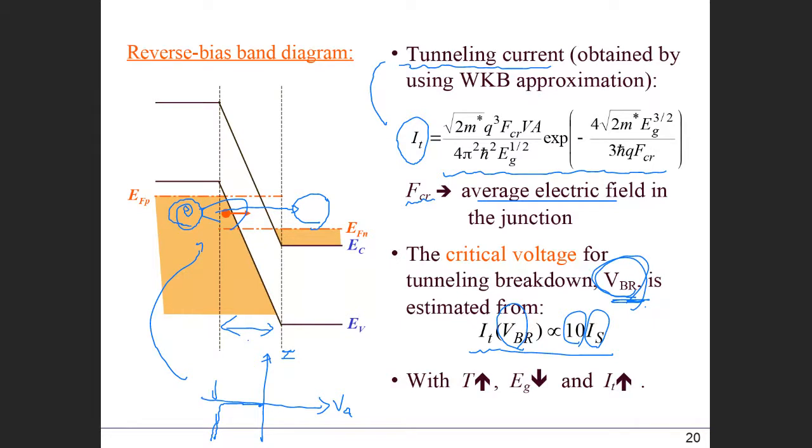For this device, we can set it so that when the reverse bias reaches a certain level, it starts to flow lots of current. Later on, I'm going to show you as an example that this kind of device is very useful to form a voltage regulator, which regulates at a certain voltage level on the upper side. So that is the basic mechanism for this Zener diode.